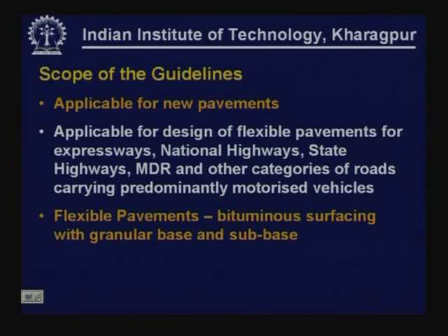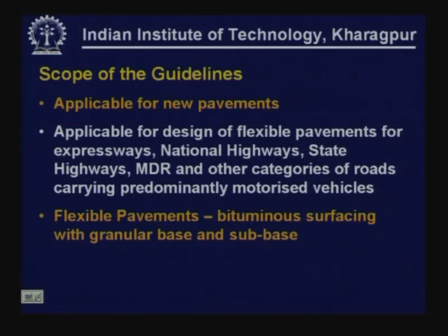Also, these guidelines are applicable for design of flexible pavements for relatively high volume roads such as expressways, national highways, state highways, MDR, ODR and other categories of road having relatively high volume. What we are trying to indicate here is these guidelines are not meant for designing low volume roads such as village roads. Also, these are obviously meant for flexible pavements typically having bituminous surfacing with granular base and granular subbase.